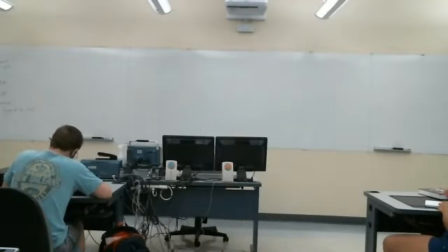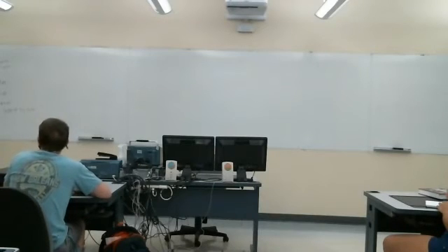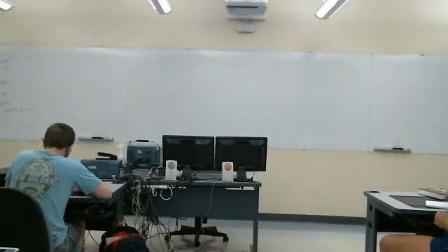That's the definition of impulse response. Well, delta t comes along at t equals 0. You wouldn't expect any system to be able to produce an output before the input arrived. That's essentially causality. So h of t has to be 0 for all t less than 0.